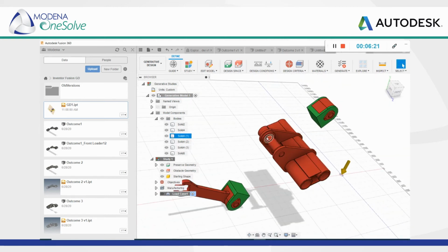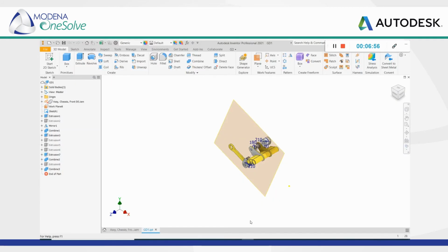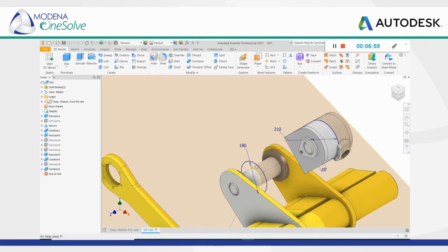That hasn't been designed. So like I said previously, we can transfer data from Inventor to Fusion via the Fusion desktop connector, and it bridges a live link. So what happens in Inventor will then populate through to Fusion 360. So remember, this is a bi-directional workflow. It's not one way. Changes made in any of the applications will reflect in the file. So it doesn't just work from Inventor to Fusion or Fusion to Inventor. It's bi-directional. Okay, so that part still needs to be created, and what I'm going to do is head over to Fusion and make those design changes and quickly create the pivot axis for the arm over here.